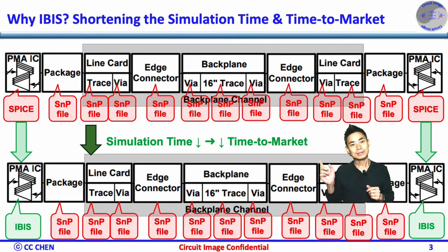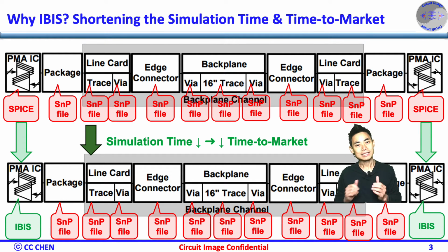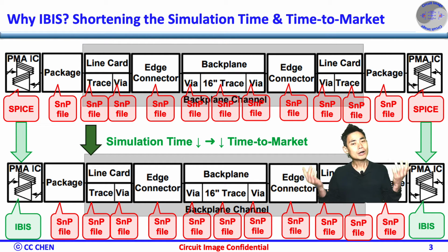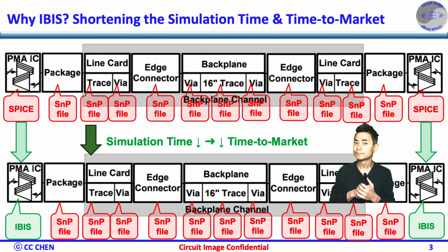For example, the system designer needs to evaluate the signal integrity, SI, in the design by accurately simulating I/O buffers, IC package, termination, connectors, and circuit board traces, etc. You can imagine identifying SI-related issues during such iterations could be very time-consuming with the SPICE model, not to mention providing a few fixes or improvements in the design iteratively.